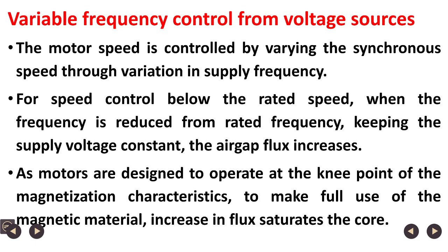So, if the supply voltage V is kept constant and frequency is reduced, then flux per pole phi increases. And as you see, as motors are designed to operate at the knee point of the magnetization characteristics to make the full use of the magnetic material, increase in flux saturates the core, because BH curve is nonlinear.